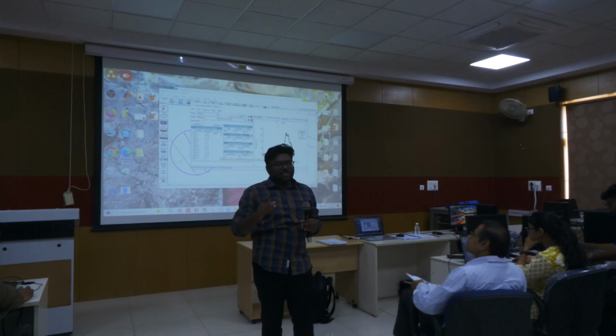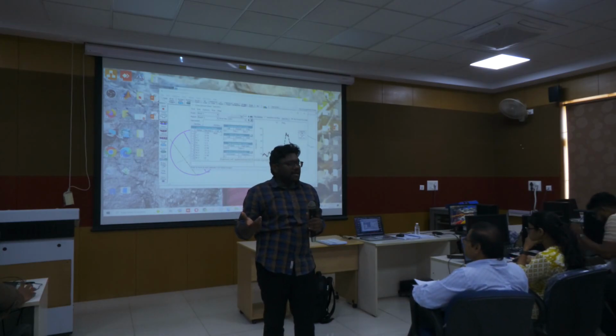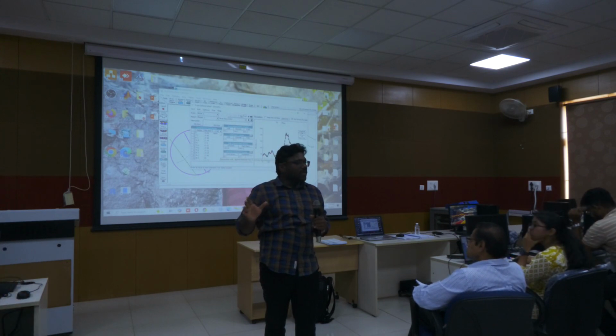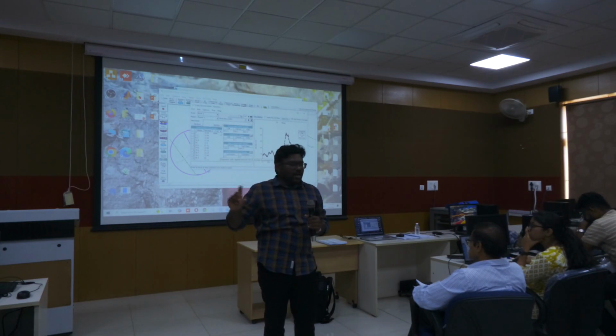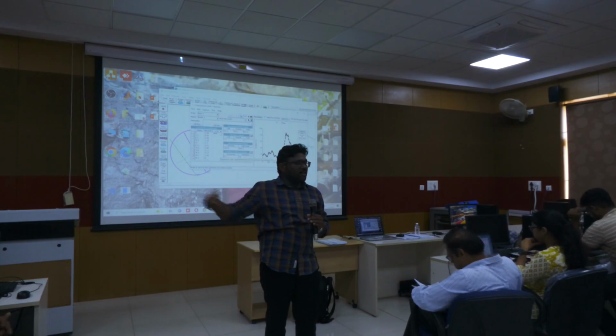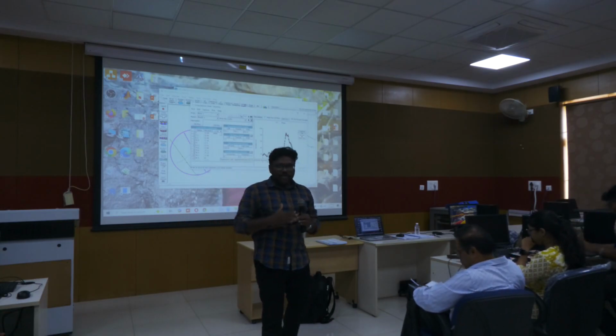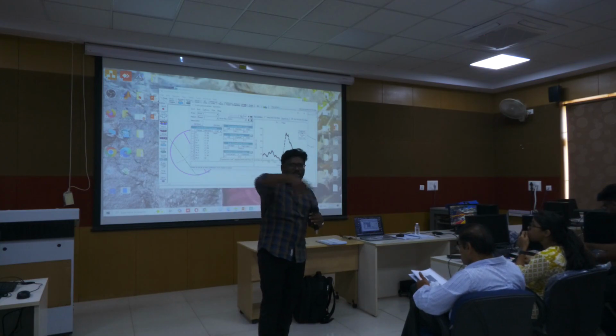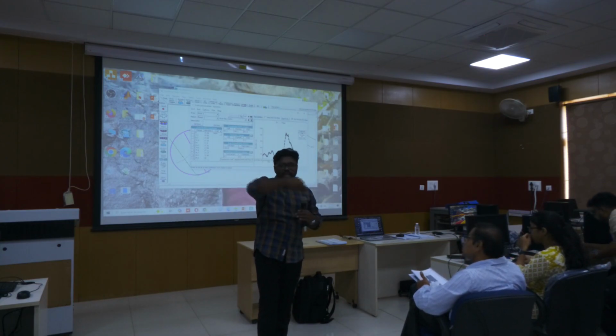So actually we have to get that data from authorities. But as of now, we don't know the exact surface roughness value, that Manning's n value. So we are assuming that we will give a smooth roughness value at the main channel, and somewhat more roughness value at the bank lines. And we are assuming that throughout the cross section, that roughness is not varying.